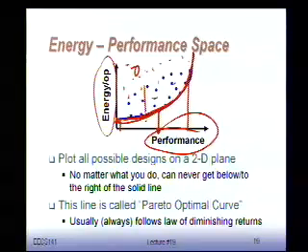They say, okay, here's where a Pareto optimal curve is, and then it's basically your job to find out what design meets that particular requirement. But it's always good to keep that in mind. Design is always this trade-off game in the energy delay space. That's where we're playing. Trading off delay for energy and vice versa. And we know there's always an optimal curve that's out there.